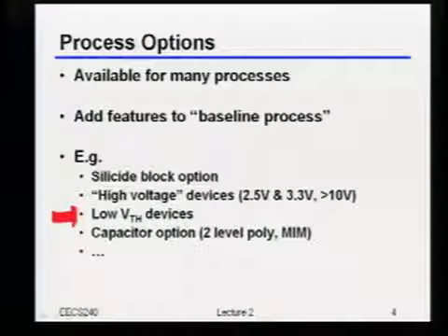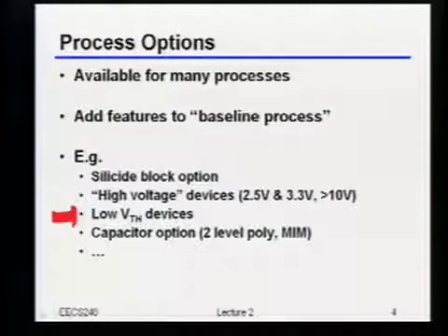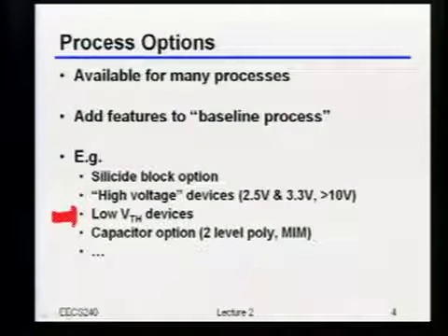Or in fact, sometimes you can even get so-called zero VTH devices, where the threshold is kind of set to 0 or maybe even negative. So that even if you put a very small voltage across the gate to source, the device will sort of conduct some reasonable amount of current. So again, potentially sort of useful in the analog space. Unfortunately, I would not recommend you use them too often.